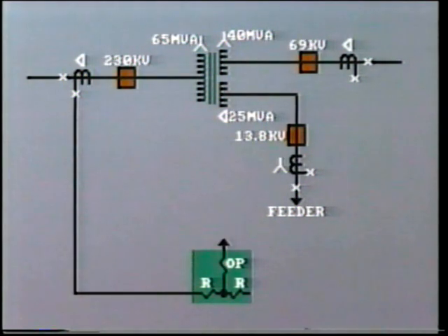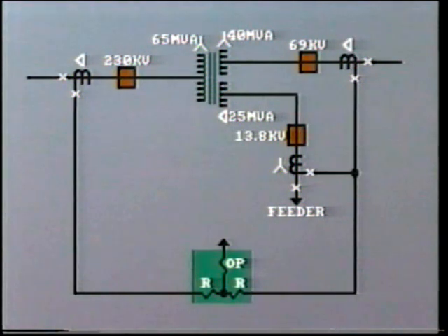How would we handle this transformer differential protection if the differential relay had only 2 restraint coils per phase, like this? In this case, we would have to parallel the CT from the third winding with that of the second. As long as the load in and out on all 3 windings balanced, this would be acceptable. But supposing we had to operate this transformer with the high voltage primary breaker open.